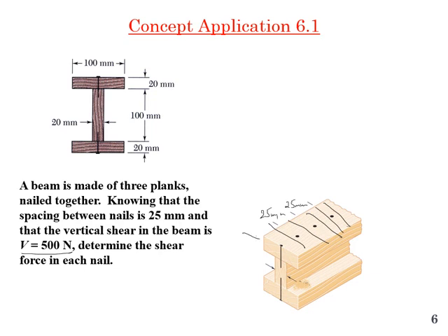If we remove the top plank and draw it, what is the shear force acting on that surface? Obviously that shear force will be acting on the nail as well, because the top plank and the middle plank will try to slide on this surface, and that will cause shear force on the nail. We have to find the shear force on that nail.